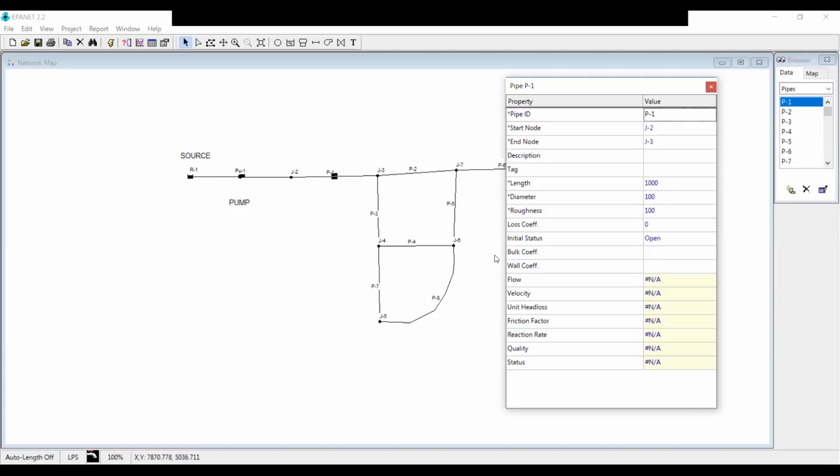Rajab, can I ask a question? Yes. What is the C factor in the handout? It's written for the pipes. There are C factors. As 100. You will write it here for the Hazen-Williams formula. It is a constant described for materials. Is it the loss coefficient? No, we cannot directly say it.